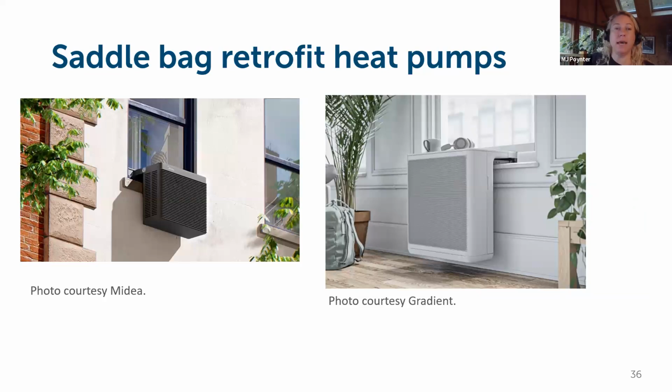The most exciting is the saddlebag retrofit for heat pumps. This has come from the New York Housing Authority, the Clean Heat for All Challenge. They put out an RFP asking for someone to develop these saddlebag type retrofits. There is a ton of housing in downtown New York City where you've got steam boilers, steam radiators, and they want to electrify and provide some air conditioning. And these units are available with natural refrigerants. They're available in 120 volt. You can plug them in. Some of the first pilots are happening within the United States to see how well they're working. And I figure in a couple years, they'll be available for the Vermont market as a retrofit application. They're really neat looking. They're very clean looking. And hopefully we'll be able to use them in some housing, maybe some public housing in Vermont.